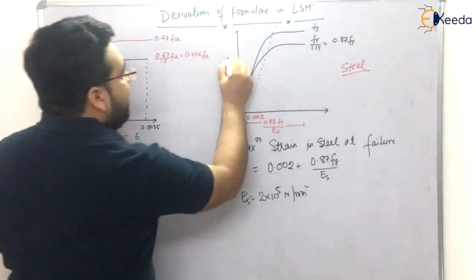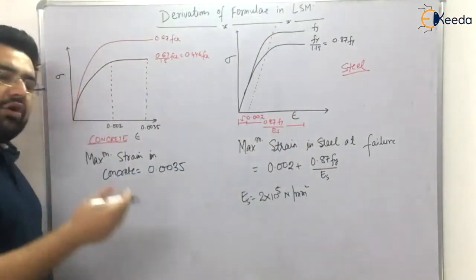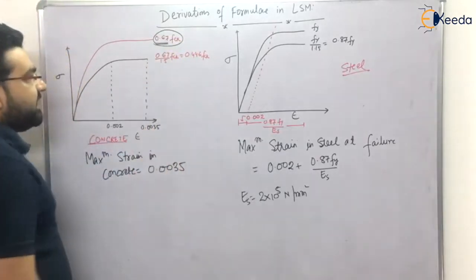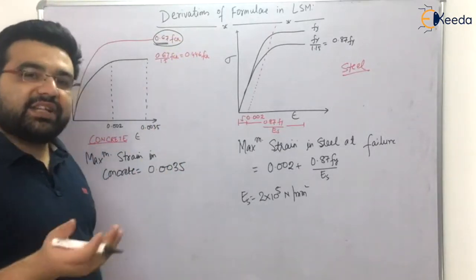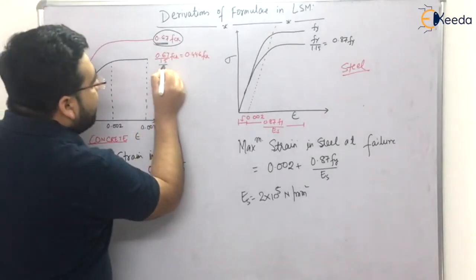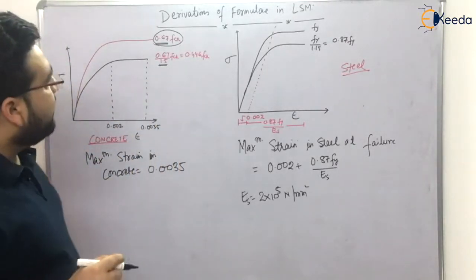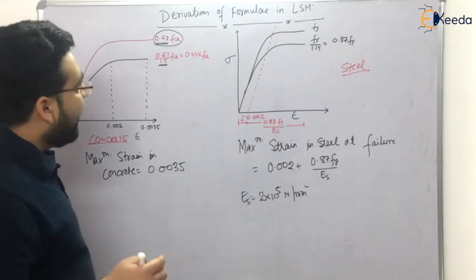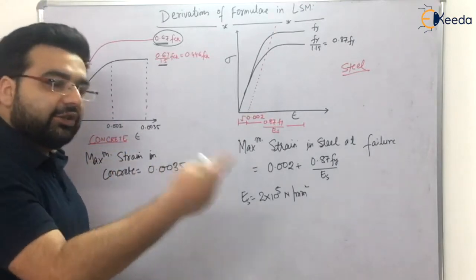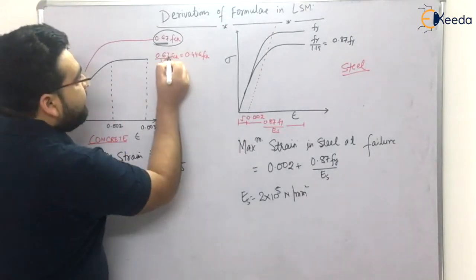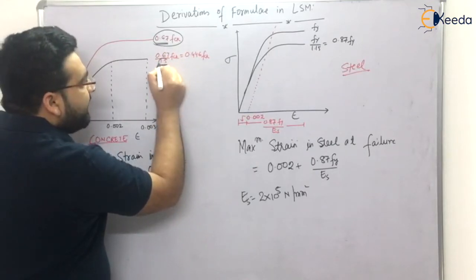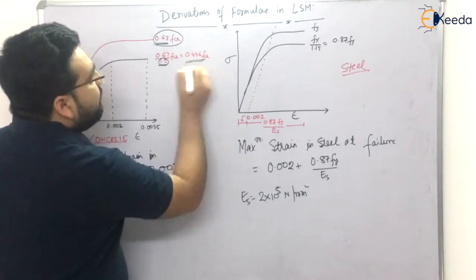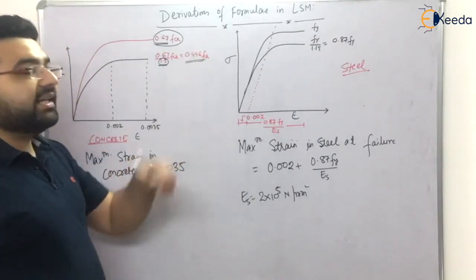Now, this is the stress strain curve for steel. I have already explained these things, right? Now, in the case of concrete, it is 0.67 fck. How did 0.67 come? Due to size and shape effects, right? And I divided by 1.5 because I told you that the main advantage of limit state method is that it has two partial factors of safety. First of all, with load, and second with the strength. So here, if I divide the characteristic strength with partial factor of safety 1.5 for concrete, I get 0.446 fck. For this, I have to design the structure.